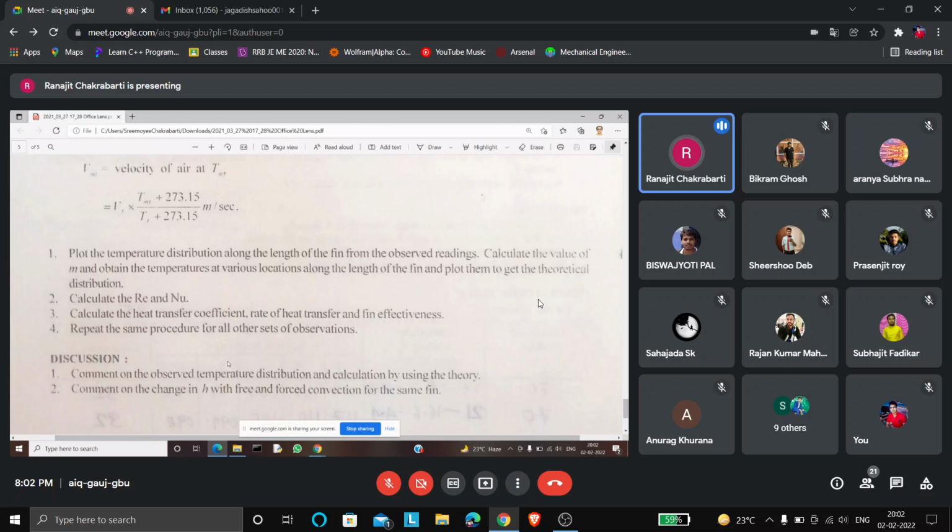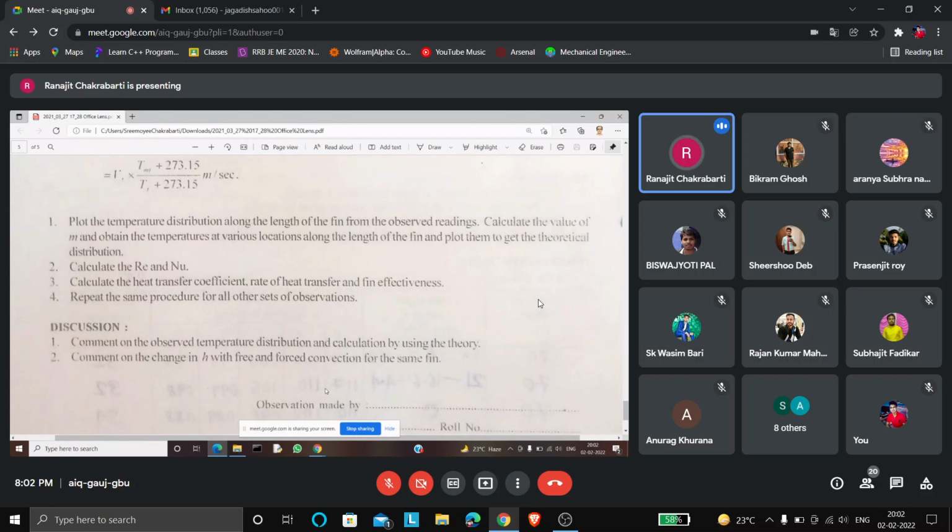Here we have got forced convection. Free convection is not there. You just write the comment that the value of H will be much lower for free convection. So how does it increase the heat transfer rate for forced convection? For that, you have to justify that H increases because of forced convection, and also in case of turbulent flow, this H becomes maximum. So the heat transfer rate is also maximum. So that you write, and that is the experiment.